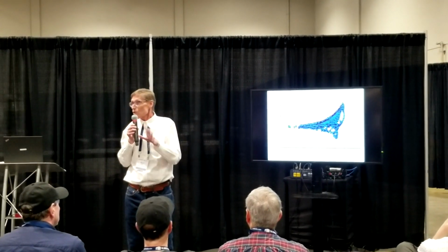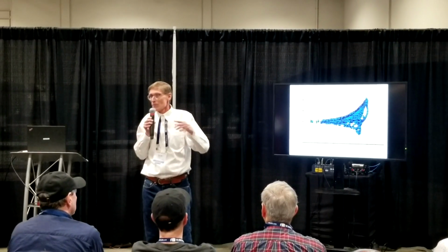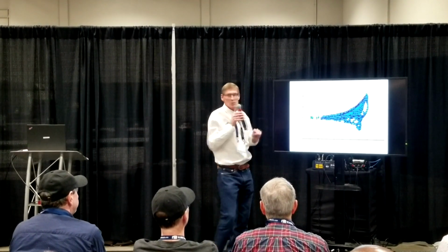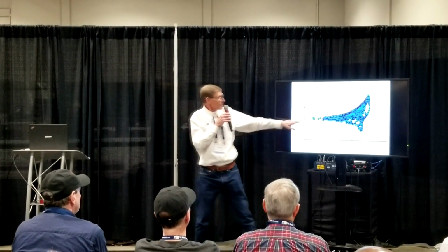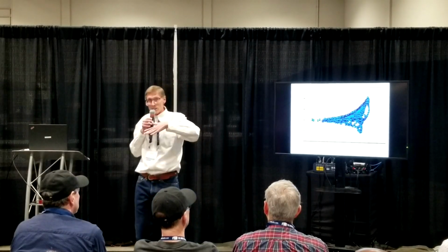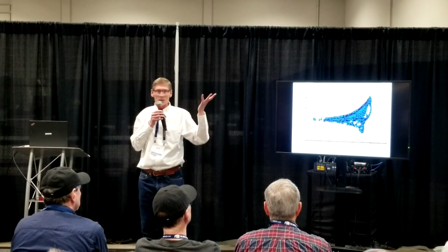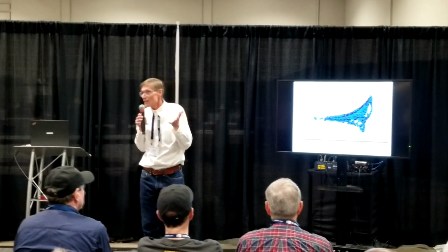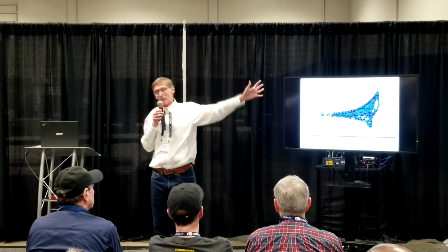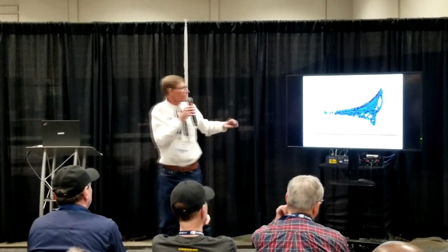Because impedance is what? It's a vector, right? You have a magnitude, and you have an angle. It just so happens this magnitude here is mostly resistive. This magnitude over here, that's still 100 ohms in magnitude, but it's at a highly reactive phase angle, so I get a lot of reflection off the load because the load says I hardly see any real resistive energy here to accept, so I'm going to let it bounce off and go somewhere else until later when it's more resistive.